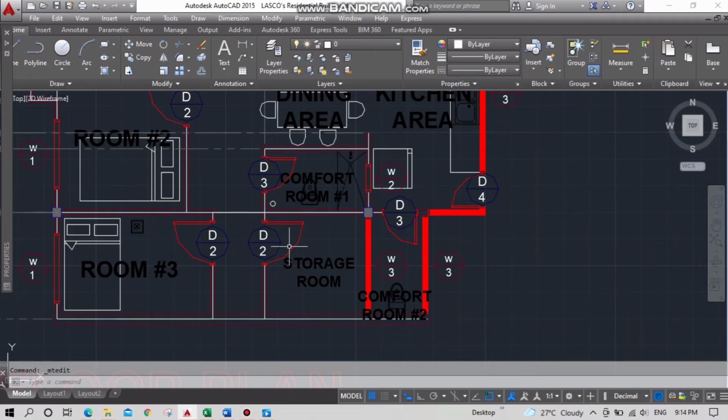Kitchens with 3 square meters with at least dimension of 1.5 meters. So, for the kitchen, yung area namin is 8.14, wherein 3 square meters lang ang minimum. So, since 8.14 is greater than 3, therefore, okay siya. For the least dimension namin is 2.2. So, okay siya since according dito, 3 square meters ang kanyang least area sa kitchen. So, okay. And then the least dimension is 1.5 meters. So, sa amin is 2.2 yung least dimension niya. And then yung kitchen area namin is 8.14.